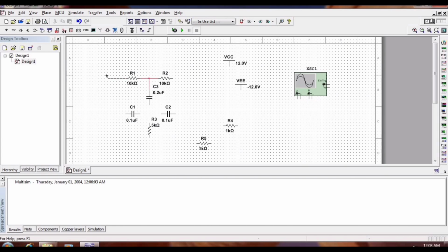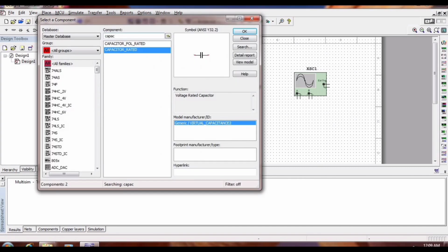Now I'm going to connect the TT network. You can see you have to move the mouse properly. Once you move here, you have to click, then you have to move. You can see you have one T network and another T network at the bottom. So you have two T networks, so it is called a twin T network.